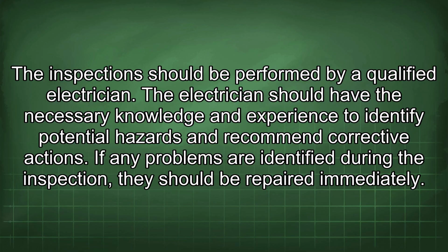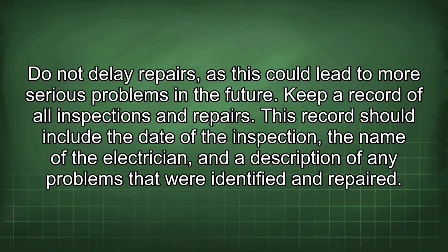If any problems are identified during the inspection, they should be repaired immediately. Do not delay repairs, as this could lead to more serious problems in the future. Keep a record of all inspections and repairs. This record should include the date of the inspection, the name of the electrician, and a description of any problems that were identified and repaired.